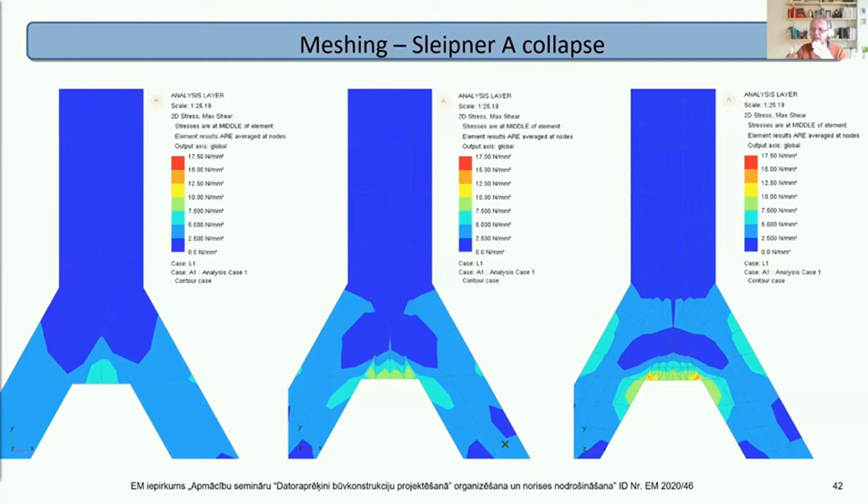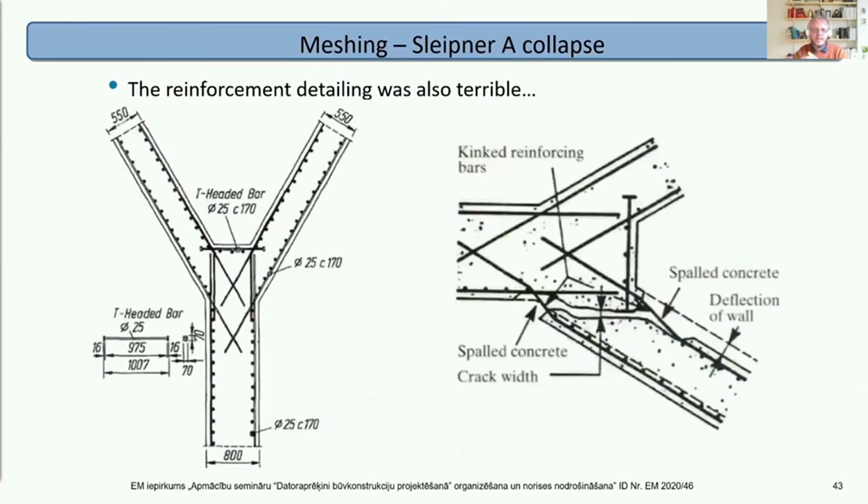So in this situation where you've got these sharp corners, if you put the mesh too small, it will give you results which won't be reflected in reality because the stress will be relieved in some way, hopefully in a controlled way, or the stress was relieved in this situation as well in a less desirable way.